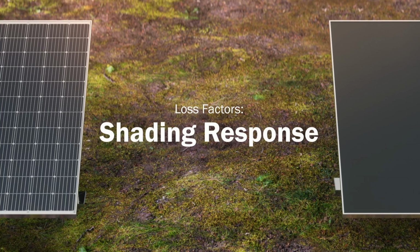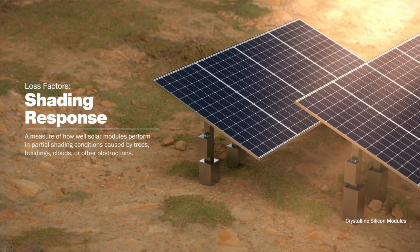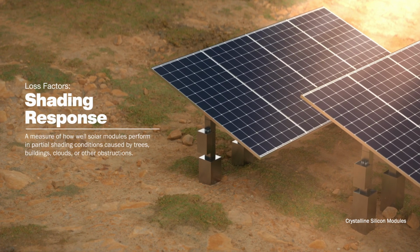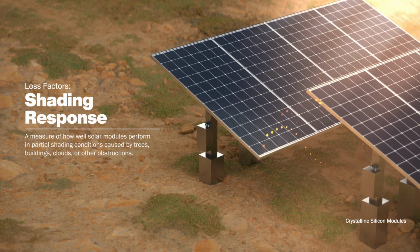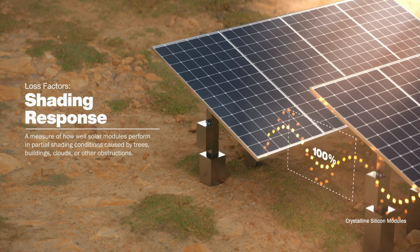Another factor to consider is shading response, a measure of how well a solar module performs in partial shading conditions caused by trees, buildings, clouds, or other obstructions. Even a small amount of shading can reduce the power output of a solar module due to the way the cells are connected in series and parallel circuits. That's why crystalline silicon modules are often designed in a way that can redirect current around any shaded cells.